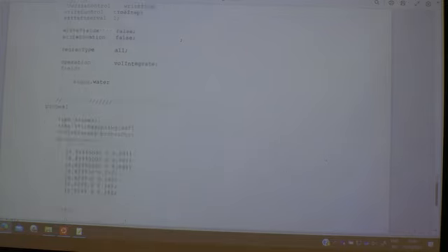Not for every single time step, that's not necessary. And also it's going to smear out the entire figure. But say at every second, I want a plus minus error bar. So how do you do that? Well, if you look at the GCI description, typically you have to evaluate for, say, one given time. And I would suggest time 2 seconds. Then the entire box is covered with water. So use that one as a monitor value for the different probe locations in your GCI study.